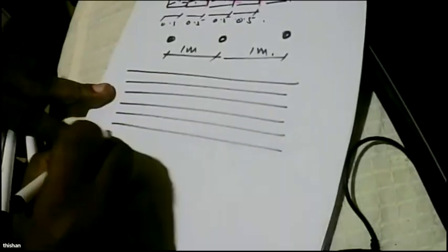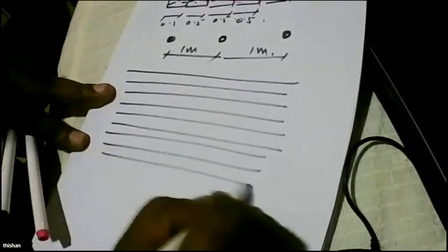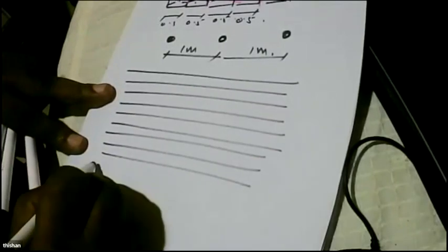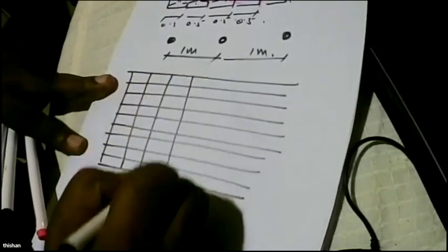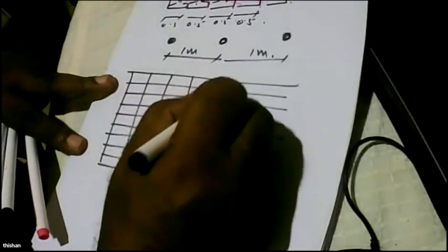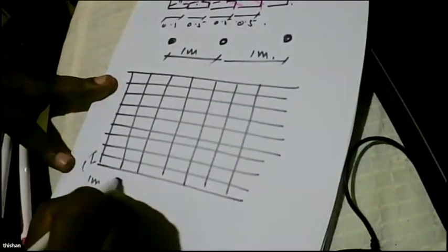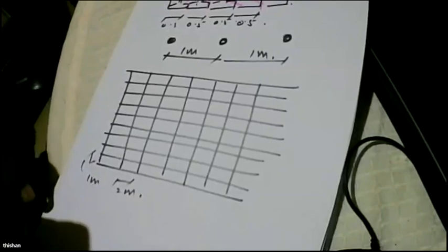So we don't really worry too much about these things, because what we do is we create a series of beams to represent the slab, because once we get the total moment, we can divide it by 2 when designing one beam. So this way we can use either a 1 meter or 2 meter interval, and even this way at 1 meter, this way at 2 meter, that is okay. That is not a major problem, right?